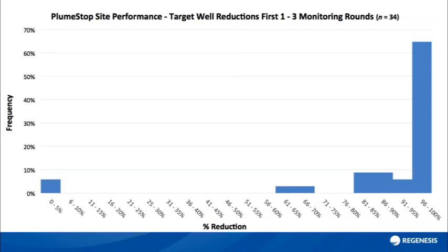We looked more carefully into those, and what we found was that there's actually two of them down in that block there. One of them was a site that performed very well over the majority of the zones. In fact, the majority of the performance on that site is right up in the top part of the histogram. But down at the bottom, we found one well that really should have had a result but didn't. And when we looked more carefully at the data, we found that it was in a zone of not just made ground, but really demolition rubble.